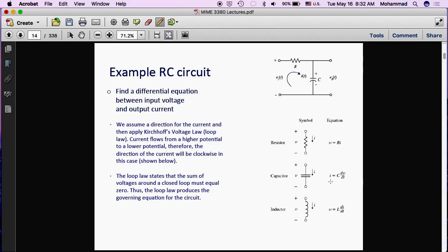And an inductor with inductance L is similar. So now here the relationship changes. If the input is voltage and the output is current, the rate of change of that output is proportional to the voltage. Can you see that? The rate of change of current as the output of an inductor is proportional to the voltage you apply. So it's not an immediate jump in the current. The current gradually goes up and will reach a steady state value.